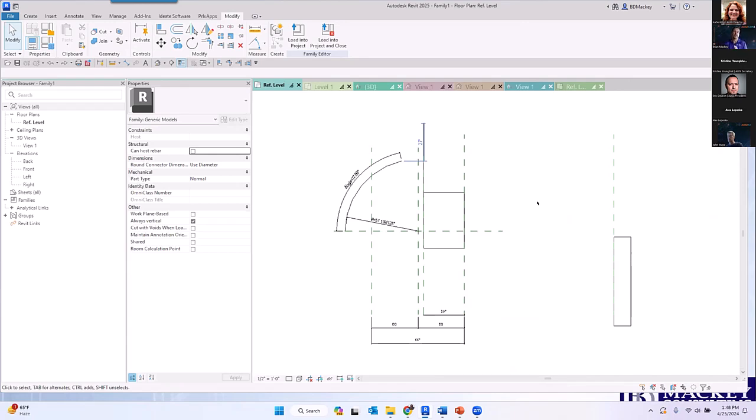Standardizing that family, I don't know necessarily what you mean. It can be like, hey, I always need this to go out to that and that to go out to that. That would be one of those things where you want this part to go out to this IFC category and that part to go out to that IFC category. If that was the case, you would have to nest your families, and I'm assuming those would have to be shared nested families.